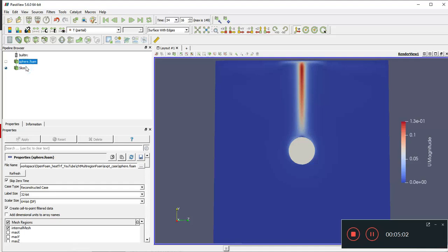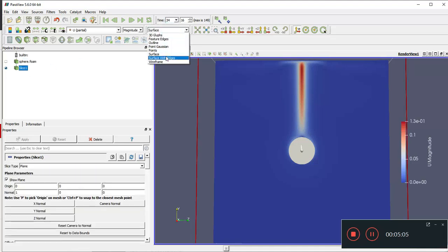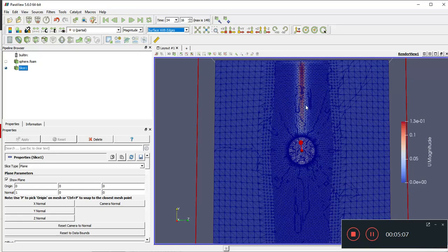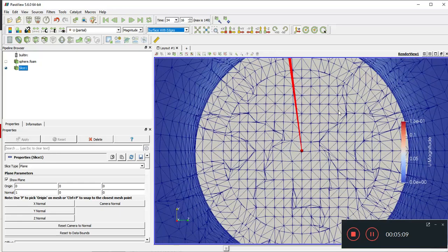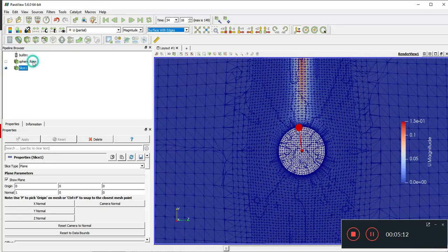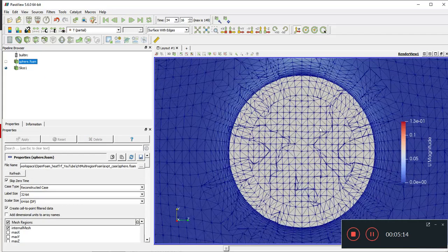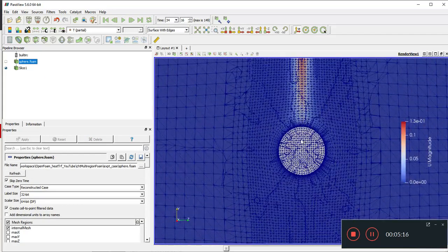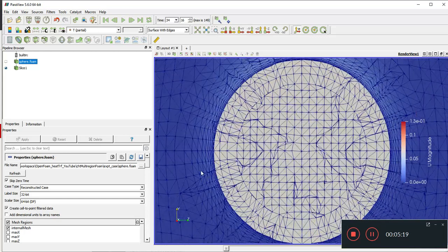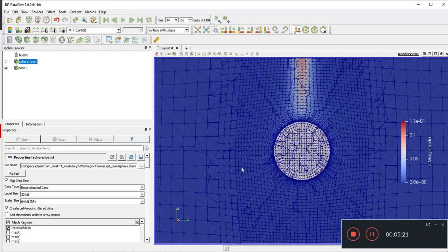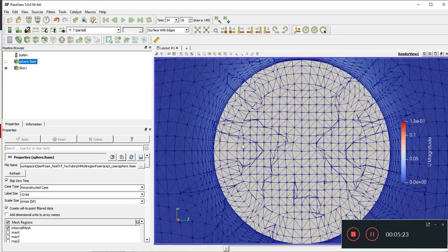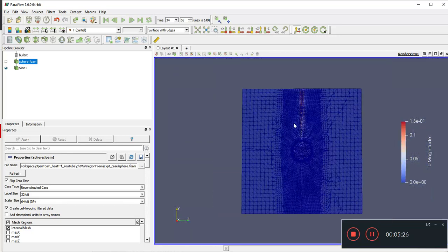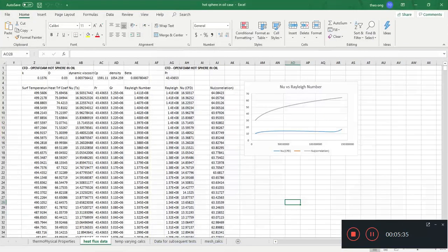And you can see it with the mesh. Very good. This is the fine mesh version. You can see with the mesh, these boundary layers are very well resolved. So the problem wasn't actually the mesh. This is a pretty decent mesh as far as meshing is concerned, when you want to resolve the boundary layers and the stuff on top. So what we want now is to compare the results.